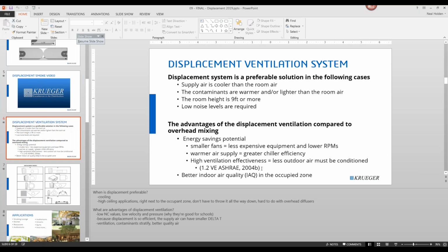So I would think that the fire damper issue would not come down to being able to integrate it into the grill, but rather into the supply duct coming into the space to enter into the grill. Correct. Yes, I think that would be something where you refer to your local codes to see where the appropriate locations of that specific damper would be.